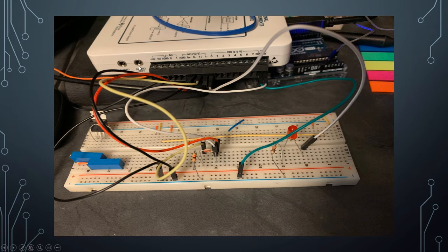I know all these wires are kind of hard to follow, but the black and green all go to ground. This red one goes to the positive analog input 0. The yellow one goes to positive analog input 1, which is reading the output voltage, and the red one's reading the input voltage. And then this white one is the digital output to run the LED that is looking for the true or false Boolean. Whoops. Got a little click happy. And then over here we just have the LED with a 330 ohm resistor connected to ground, and then our 3 ground wires.